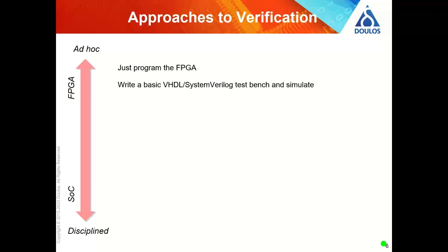So getting a bit more disciplined, we have a VHDL or SystemVerilog test bench, and we can run simulation. We can enhance that with other languages or techniques such as C++, SQL, Python, Perl, and so on. So some people like to incorporate models written in C or C++ within their VHDL or SystemVerilog simulations. So both those languages have a mechanism that allows you to easily connect your VHDL or your SystemVerilog world with C. Okay, so you could take advantage of that if you've got models maybe coming from something like MATLAB that you want to integrate as a reference model in your test bench.